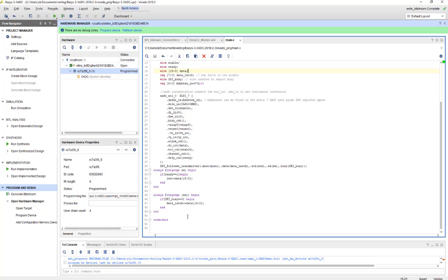You probably don't have to remember this, but I did some searching on Google. Why doesn't Vivado like it? It's because you are trying to input a signal to the FPGA, because SCK is a signal line from an external device, which is the Arduino, right? So you are trying to take that clock in and use it in your FPGA. What I saw was that there might be an issue that the internal clock and that clock don't know each other, so eventually they are unsynchronized on both sides.